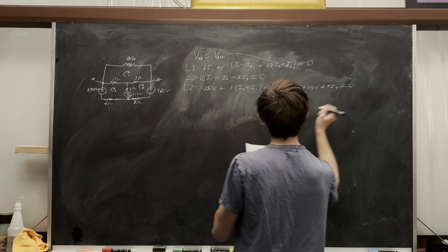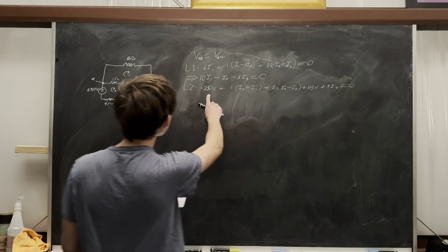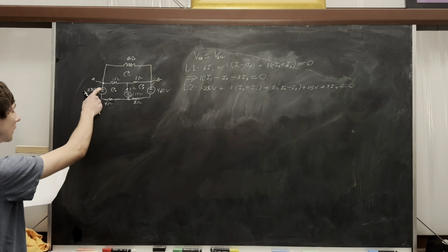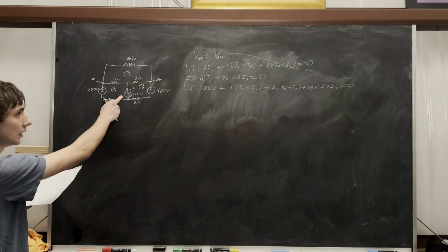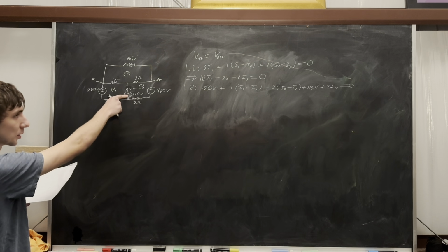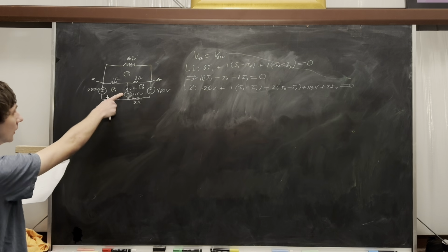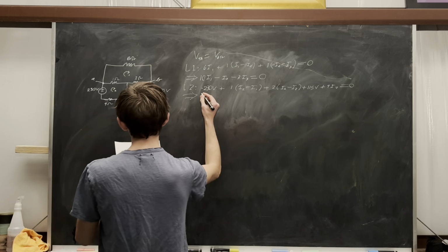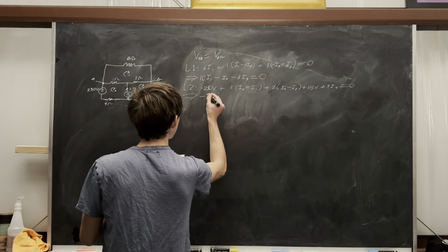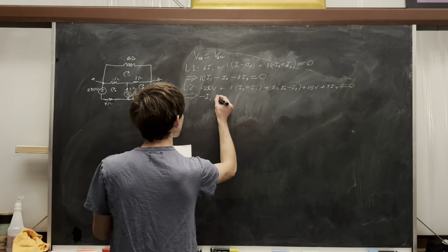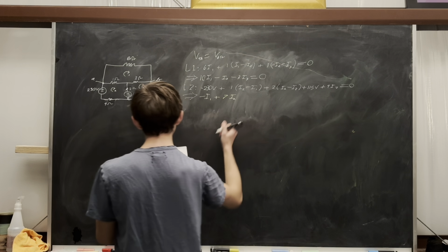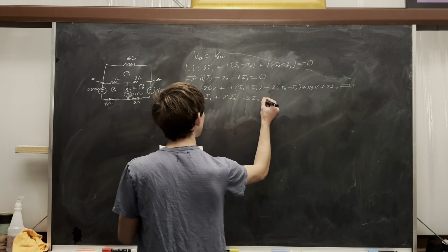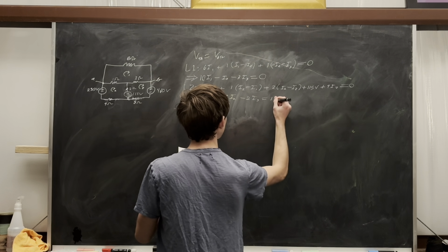That all equals 0. Notice how this voltage source, I have it negative in here because we're coming into a negative and entering through the positive. This one is positive because we're going the opposite way. The current is going the opposite way when we're looking at this one. So we simplify that equation down to minus I1 plus 7I2 minus 2I3 equals 115 volts.